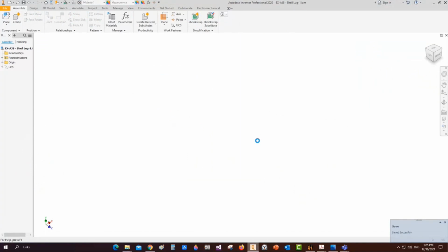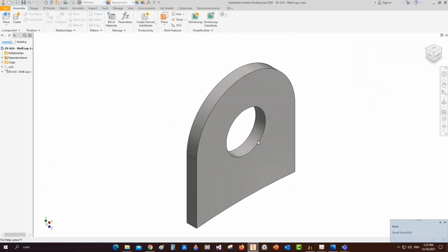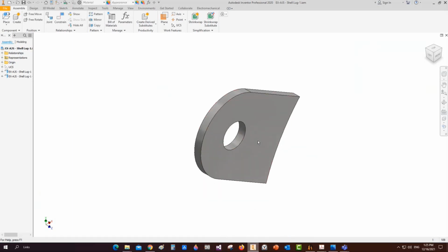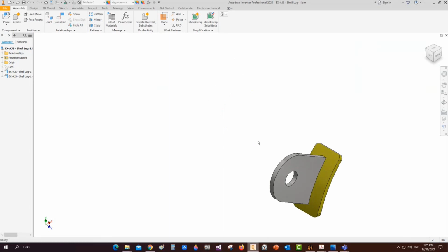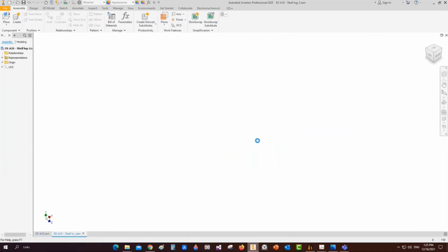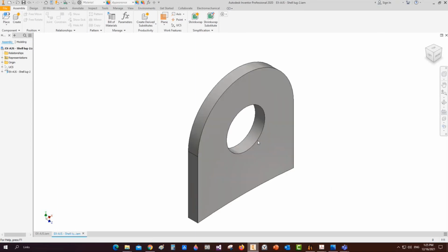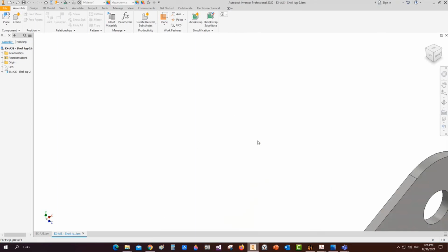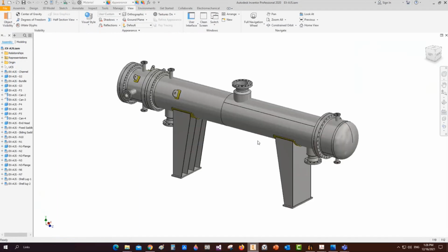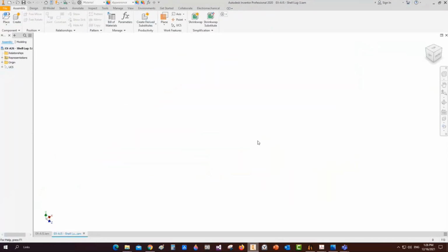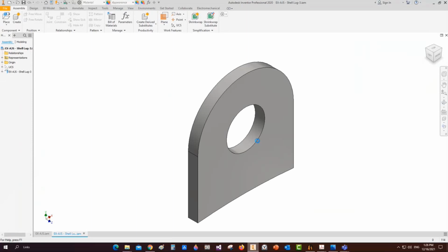After this step, inshallah, we will make the connection bolts for the flanges and the tube sheet, and add some attachments, like if we would like to add a blind to the vent hole or the drain hole, how we can make that, adding the stud bolts, adding a nameplate. After that, inshallah, we will proceed with the general arrangement drawing and some other drawings and the content of the drawing, and how we can control the content, like if we would like to export the bill of material, nozzle table, and other tables to our drawing.